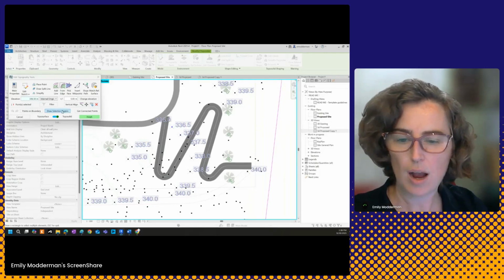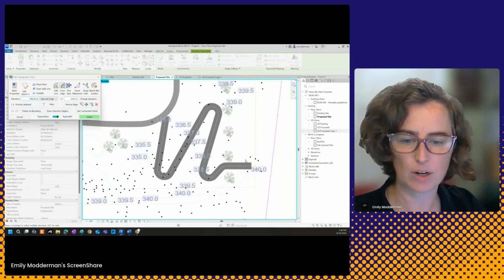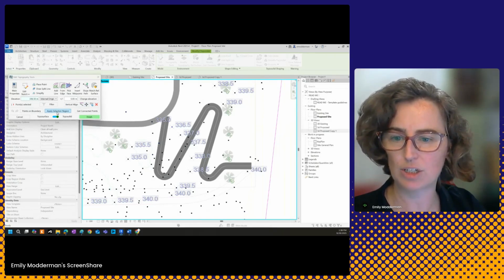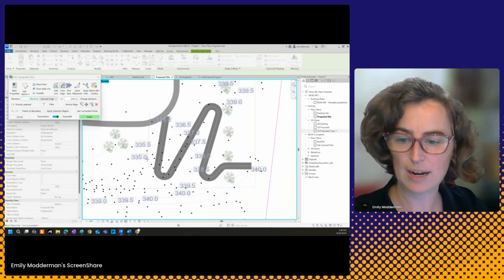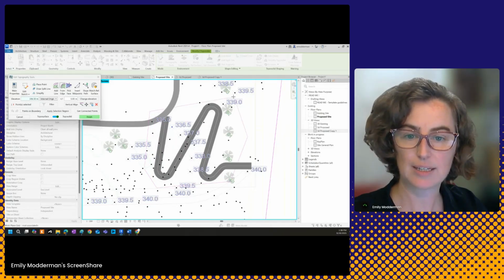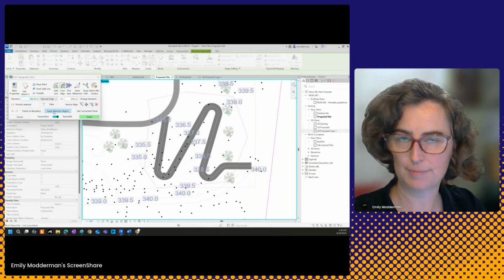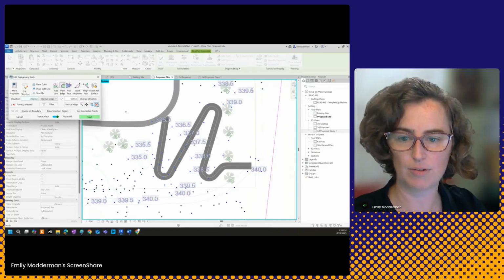And so I'm going to wipe out some of these points that are close to the path so I don't get anything a little ridiculous once I align everything. I'm going to use the Draw Selected Region tool. This is relatively new, and it allows me to fence off a region of points that I would like to, in this case, remove. So I've finished my fence. I'm going to apply that, it highlights all of those, and I'm going to use the delete key here.